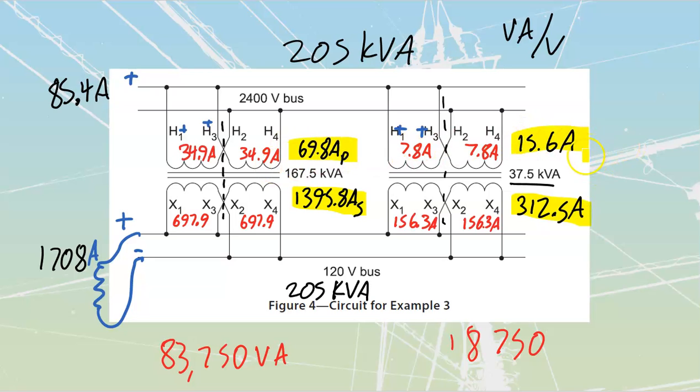Because those are going to determine the size of the fuses and circuit breakers that we're going to use to protect our transformers on the input as well as on the output side. We could place protection on either side. It's not going to be required to be on necessarily the primary, but it's very common that we're going to place it on the primary because we do know that the code has the requirement for a disconnect in the primary.